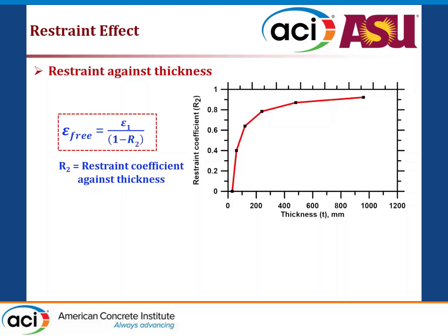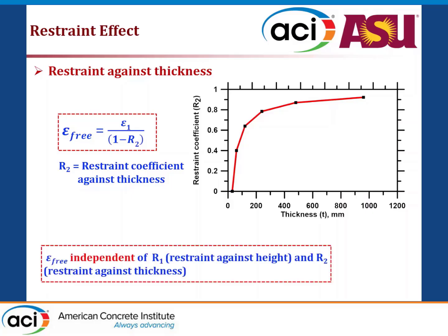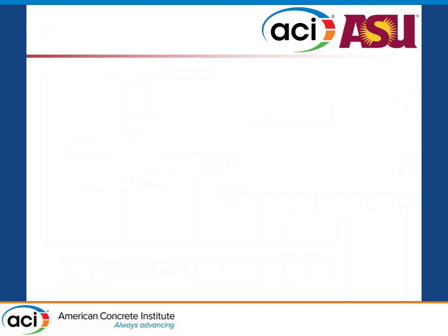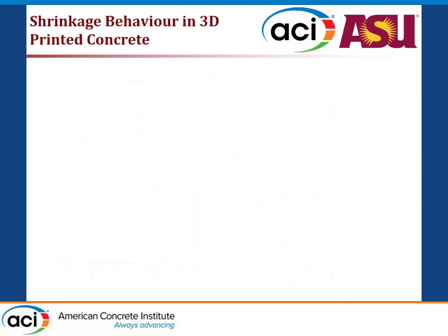Again, it's not based on a certain equation, but mostly on continuous trial and error on different mixes that we did for different layer heights. The restraint effect in the direction of thickness follows a power law. In terms of this value, it's like 0.6 times the 6 to 6.3 times the previous filament if you go twice the filament each time. When this restraint effect is calculated, we've validated it for 4 filaments also, but I'm not showing that here.